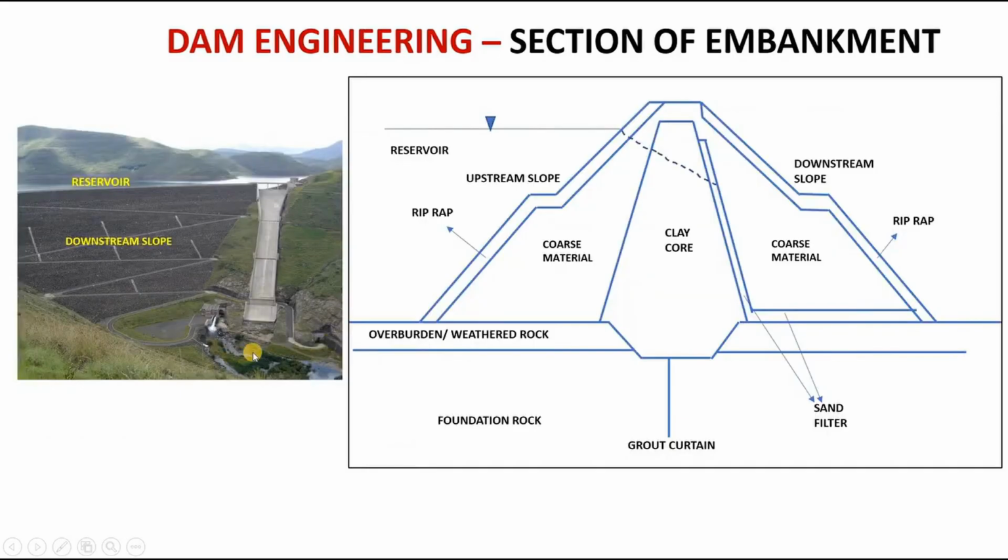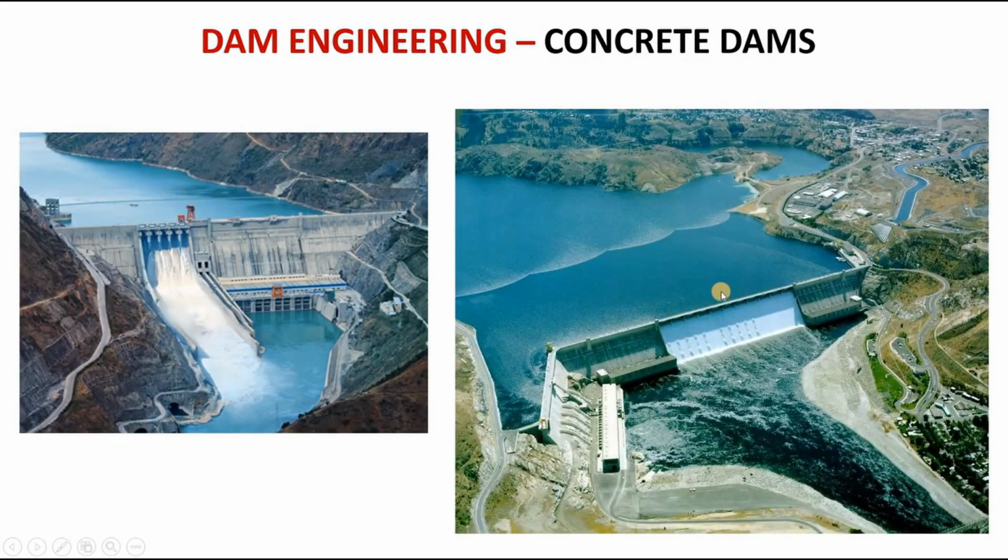If we are placing the dam on weathered rock, obviously there will be some seepage. To control the seepage, there should be some grouting. This grouting is called curtain grouting. Further, gradation of different materials in earthen dams is highly required so that the particle size increase shall be uniform. To collect the seepage and also to match the gradation, filters are proposed. Once the seepage, if any, is collected through sand filters, it is drained or collected at the downstream using rock toe at the downstream.